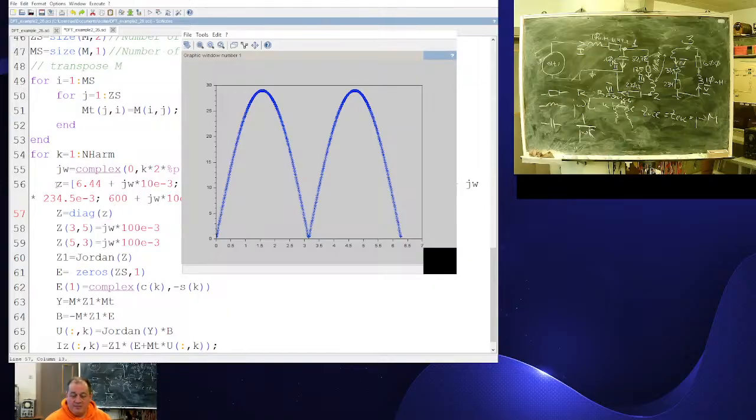This is the main diagonal of the resistance matrix: own or self resistance, inductance, capacitance of my branches. This is a near complete resistance matrix, except I need to put mutual inductance. Branches 3 and 4 are coupled with mutual inductance of 100 millihenries.